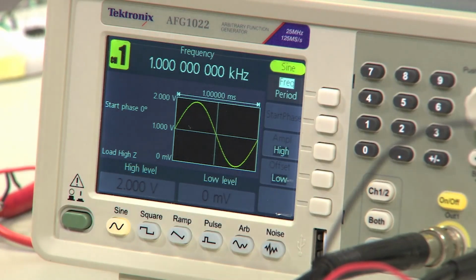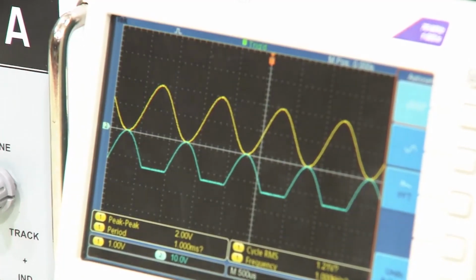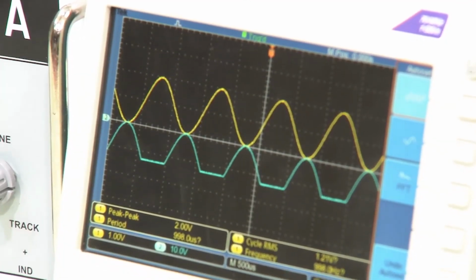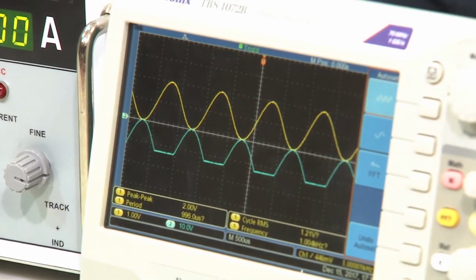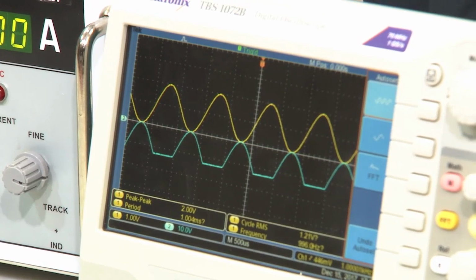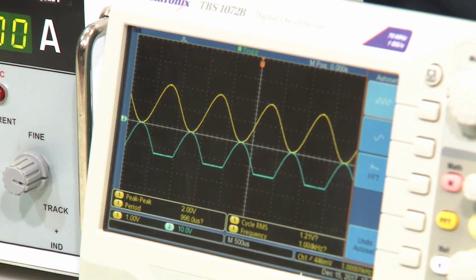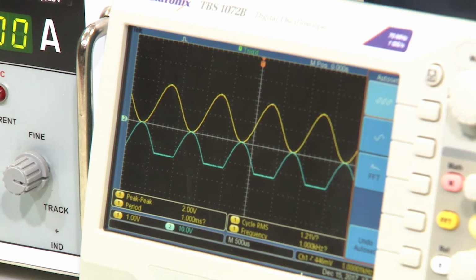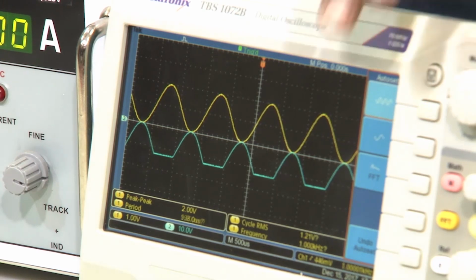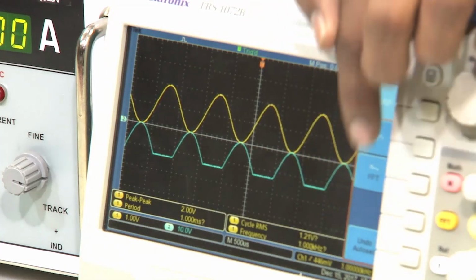When we apply 2 volts instead of 1 volt, what is the output? Let us see, alright. So, if you see in the oscilloscope, it is clipped, that is the reason that we want to apply 2 volts. Now, the first question that should come to your mind is, it amplified how many times? 2 into what is the gain? We found the gain was RF by Rin, right. So, 10 by 1 is 10, 10 is your gain. How much voltage are you applying? 2 volts, 2 into 10 will be 20 volts. So, we should see a signal which is 20 volts, and the signal is out of phase, that is correct, yellow and blue are out of phase.